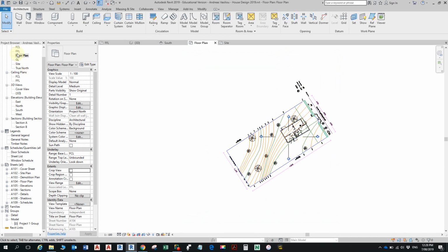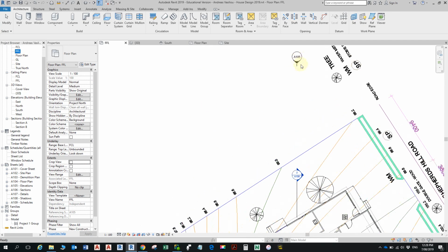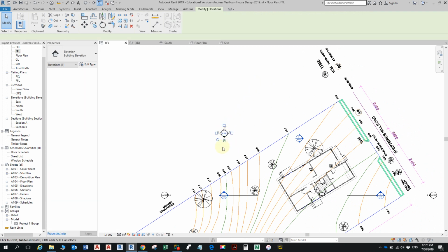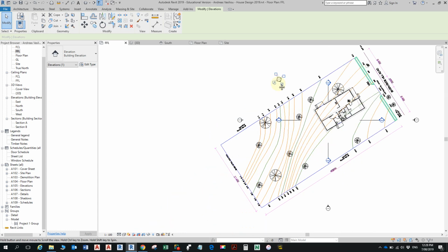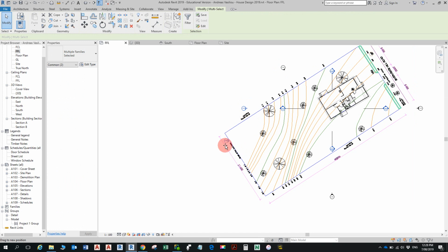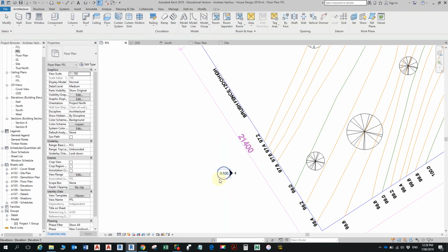Now I can't see the, I think they're over here on the FFL. Yeah, I'm looking at the elevation symbol, so I'm going to bring this one over here, and then rotate it. Click on this little thing here. It sort of locks in to about there. Roughly enough, it's more front on than it was before. So that's my new north elevation, I suppose. It's called north. I mean, it's just a name. All right, so it's not true north.